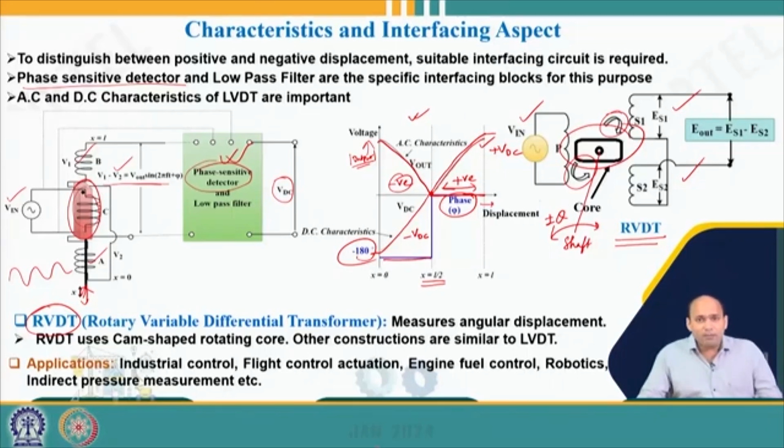How can we do that? You remember that in the previous class we discussed a pressure sensor with a diaphragm element, where the diaphragm was the primary sensing element. In order to convert that displacement into resistance, we connected a strain gauge on the diaphragm, and the strain gauge resistance changed because of the applied strain. So in that pressure sensor we used two elements: the primary diaphragm, which is the primary sensing element, and the strain gauge, which is the secondary sensing element used to convert the displacement into resistance.